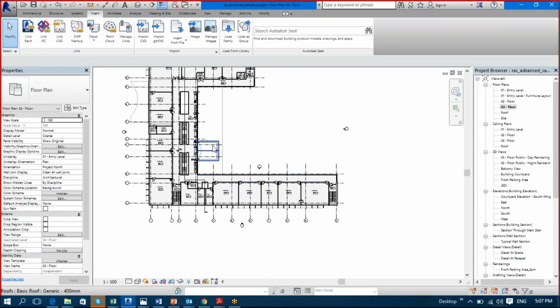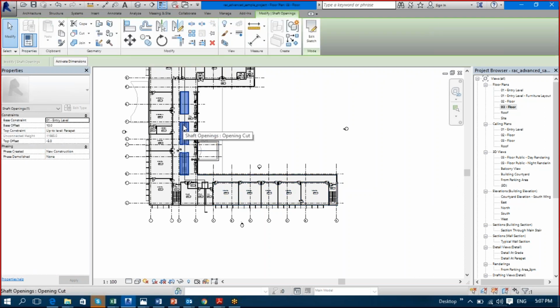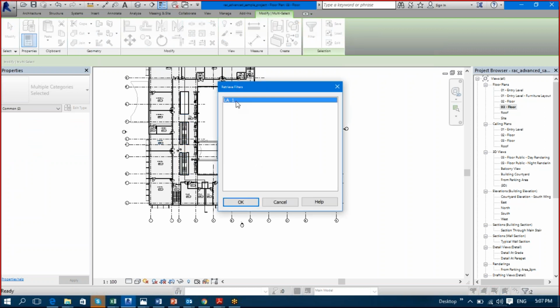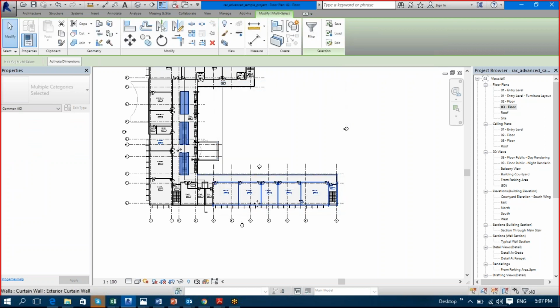Now what will happen is that if you are selecting this supposedly and you want to select this also, which you have selected in the previous part, while you are selecting like this one part, you immediately have this option called load. The moment I say load selection and LA_1 and press OK, you see what happens. With that selection, this selection also happens. So there are always specific types of selection that I want to do. What if we want only one and those three? Can we do that? Obviously you create a selection set according to it, or use the control button.